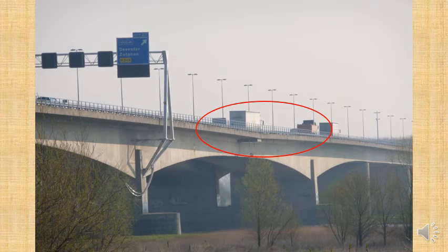What that's going to mean is that there's going to be some elastic deformation and those columns are going to be squeezed. And it's very small, as I said. It probably doesn't matter for a building like this. It might be 5 millimeters or less. But any more than that, and suddenly components are not going to align.